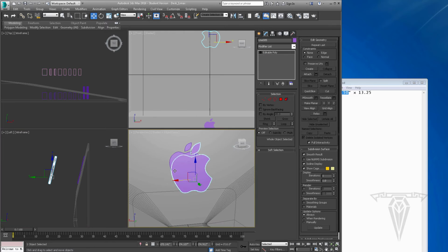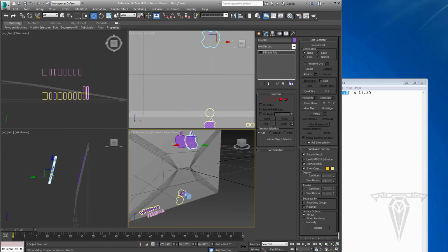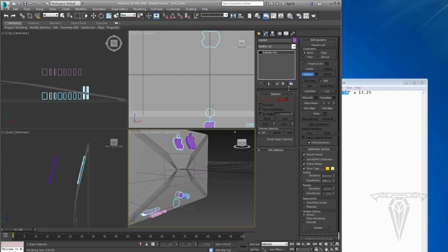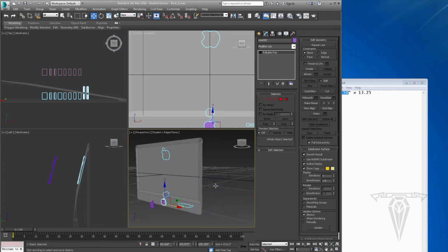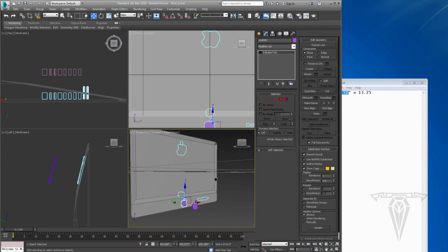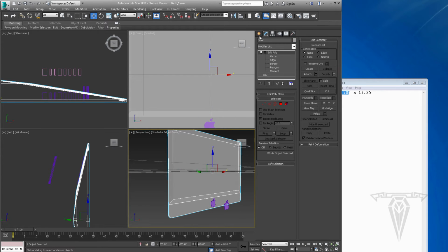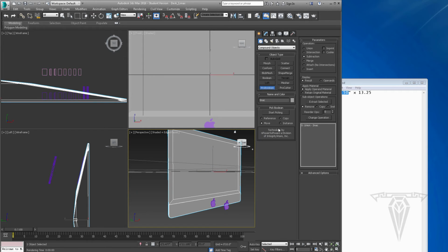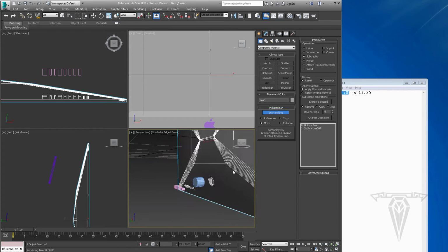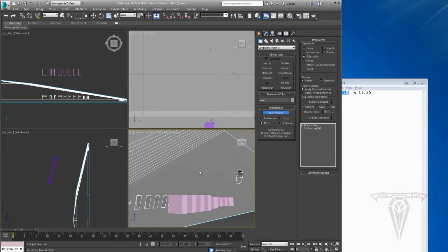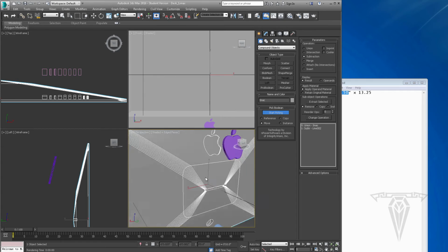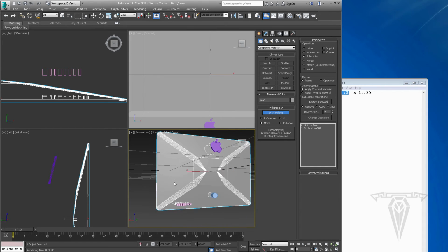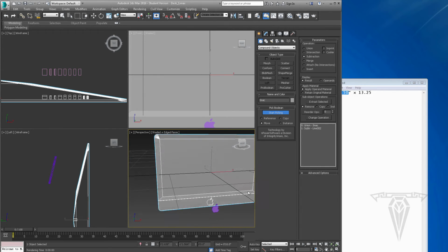Click OK. So now, let me go back to these pieces and attach. There we go. Okay, so these are all turn off, attach. All the things we're going to cut in the geometry. So I'm going to go back to here, create panel, Pro Boolean, pick, and it did a good job there, did a good job down here, and did a good job there. Voila. So now I have all my holes in my geometry.